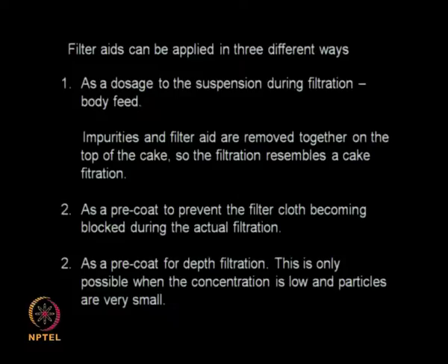So you need to consider all these aspects before deciding on the type of filter aid you would like to select, as well as the particle size of the filter aid. These filter aids can be applied in different ways. I can add the filter aid as a dosage to the suspension during the filtration process.